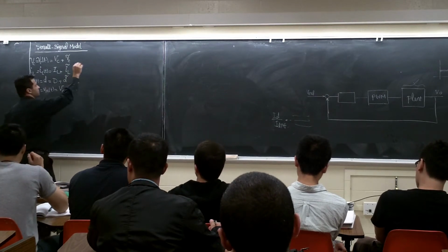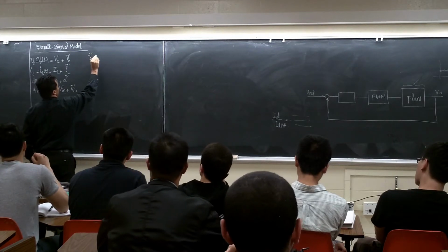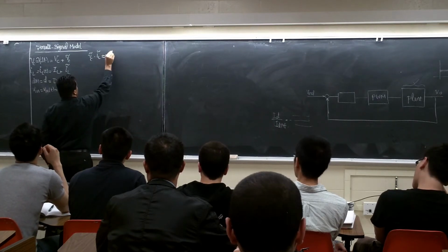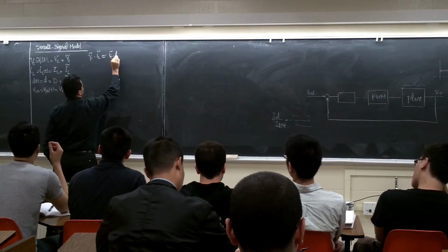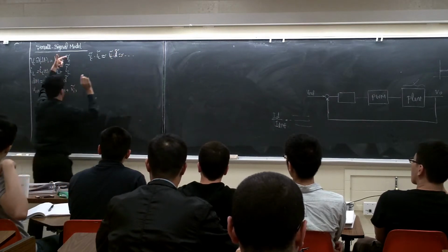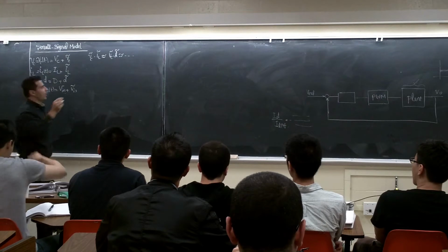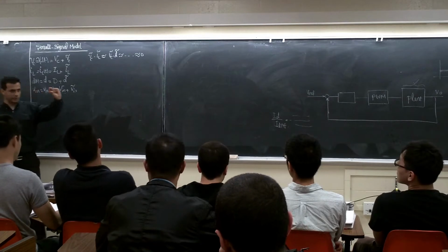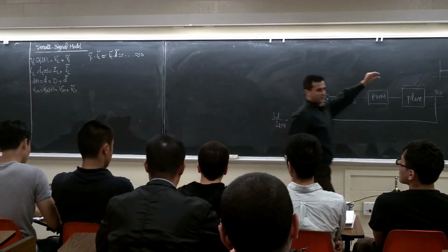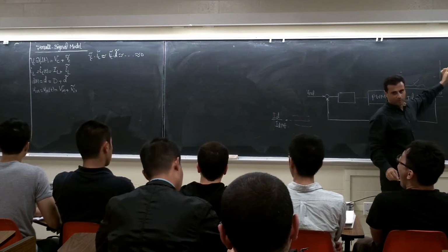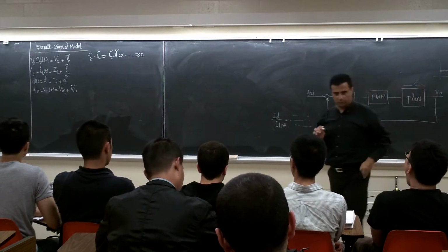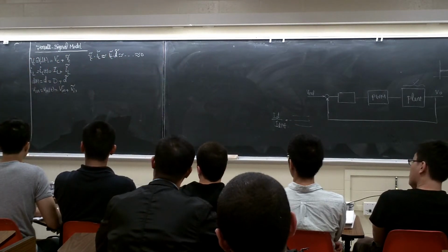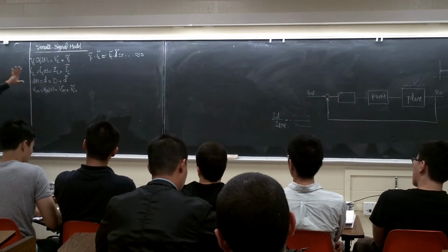Whenever I have a VC tilde times IL tilde, or VC tilde times, I don't know, D tilde, or any combination of these four, it is almost zero, because these are small changes. One small number times another small number is going to be a very small number, and we assume that it is almost zero. So any of these tildes times another tilde, we assume is zero. Keep this in mind.